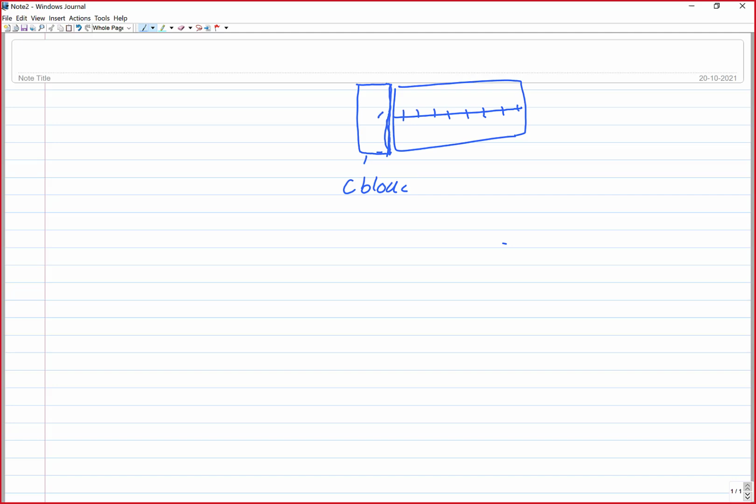The electrode is brought in contact with the carbon block, and once the arc is struck, the electrode is moved to the location where welding heat is needed. So in the carbon block method, the electrode is brought in contact with the carbon block and then quickly moved towards the location where the arc is needed.